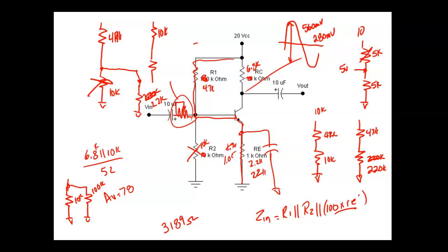So when I come over here, first of all, why did the voltage go up so much? Because now my voltage divider that's setting my base voltage looks like this. It's a 47K, and this right here is a 22K, because it's times beta. What would the voltage be right there?